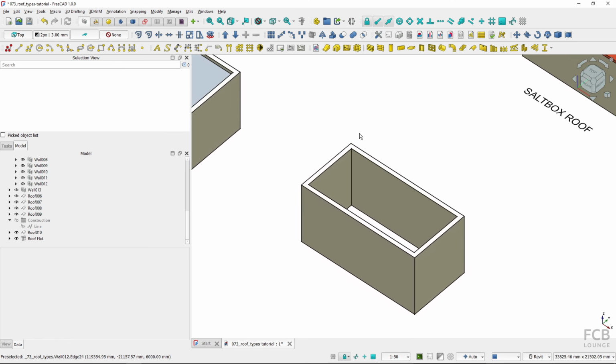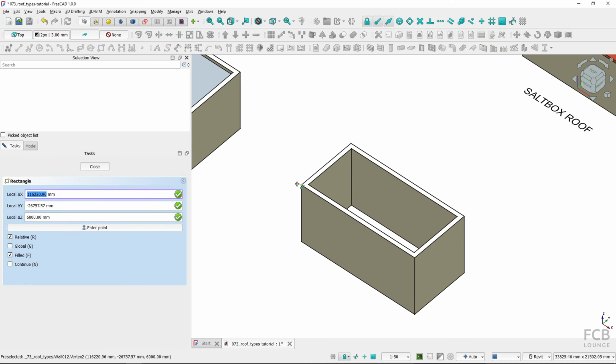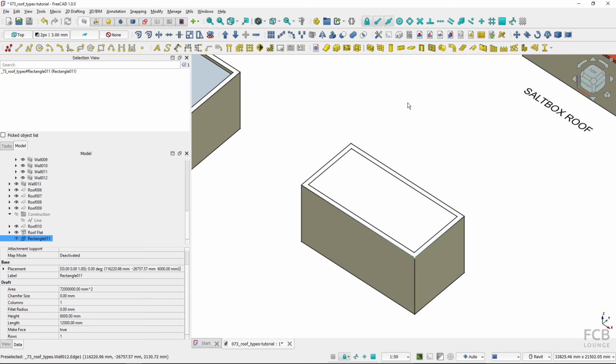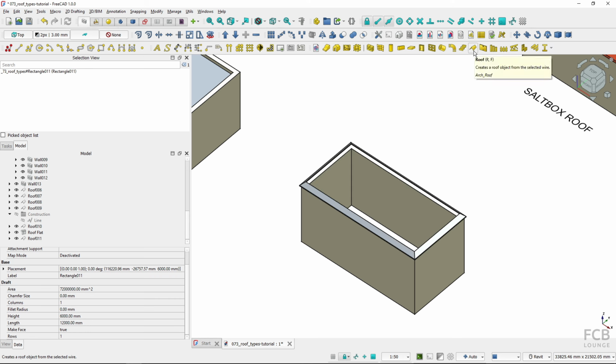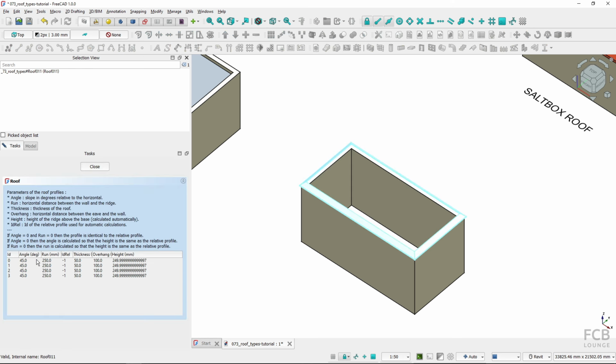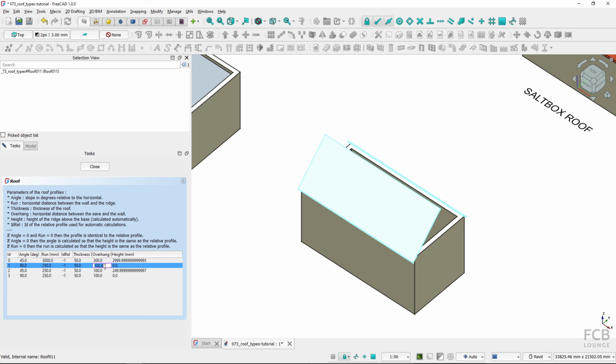As you might expect, we will first start with the roof footprint, again with the rectangle. So I will create a rectangle like so. Now create roof out of the rectangle, edit the roof, and now I will check which edges, which one, so I know that this one will have 90-degree and 90-degree angle, so the overhangs work. I can actually change the overhangs straight from the beginning. I will change all of them to 300.